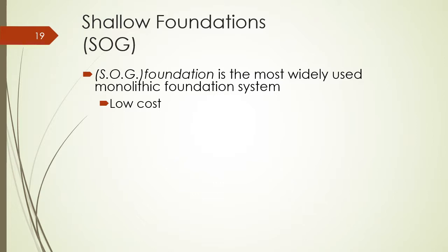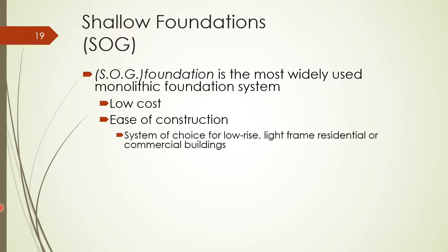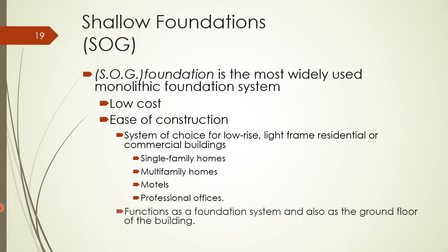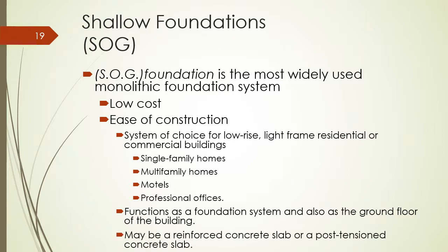It is low cost. It has our friendly ease of construction, and usually it's used for low-rise, light-frame buildings, single-family homes, multi-family homes, motels, professional offices. It will function as the foundation system and also the ground floor of the building. It might be a reinforced concrete slab or post-tensioned.